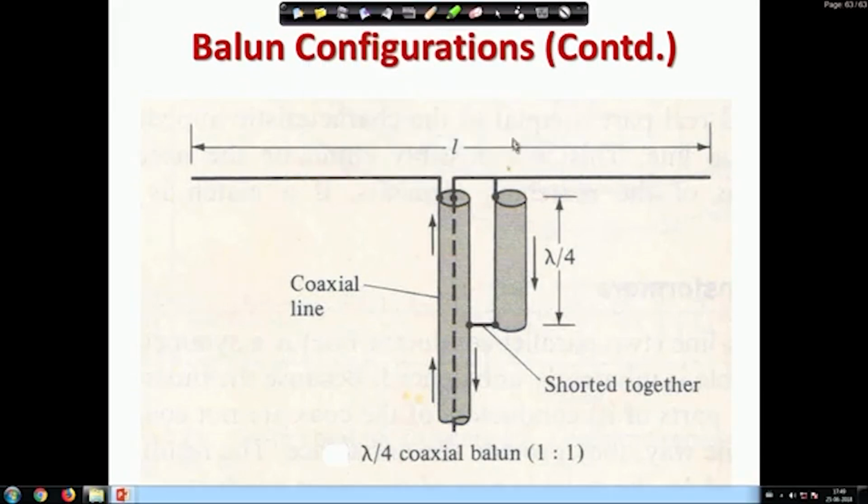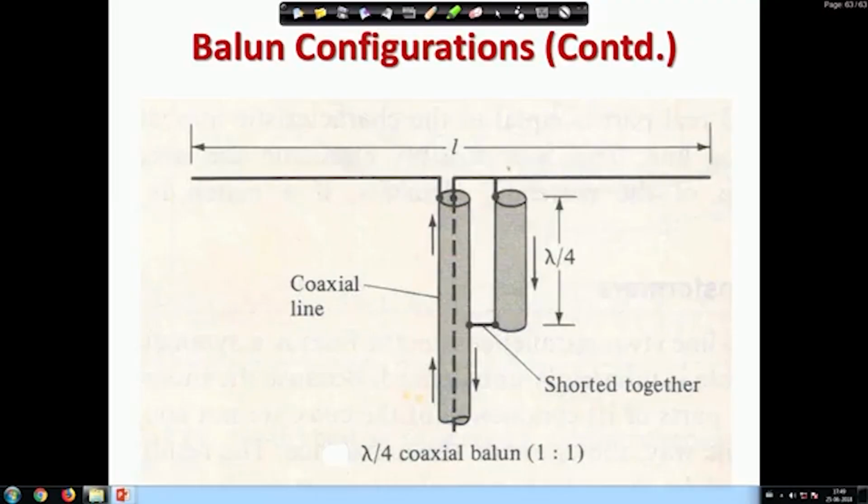So, you will typically see this in any VHF equipment, particularly our TV boxes, they have that balun. Without that balun, you do not get good reception, because the efficiency is poor. If the two currents in differential mode are not equal, then it appears that there is a lot of noise, because noise also has the same effect of making equal common mode currents.